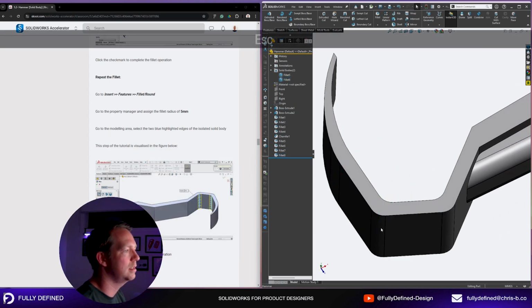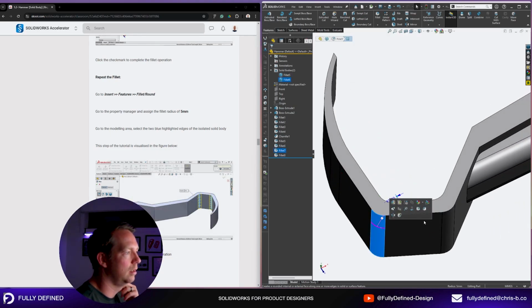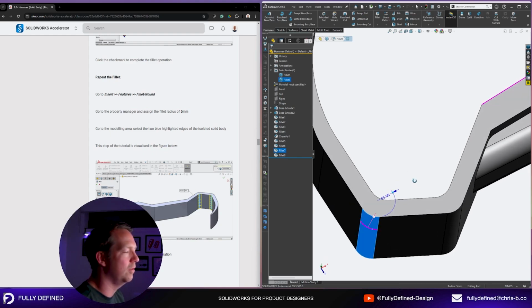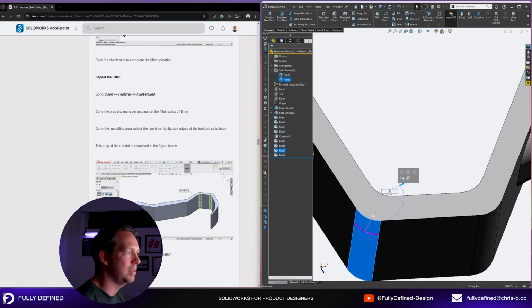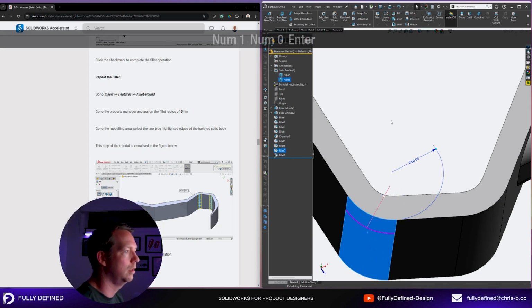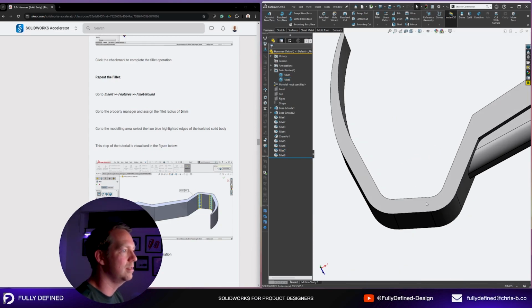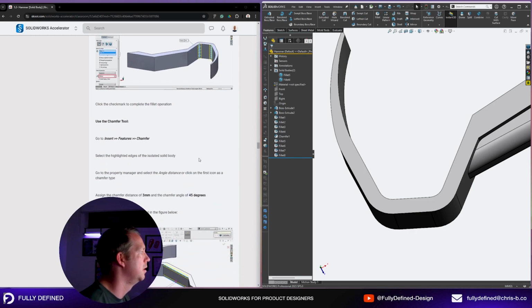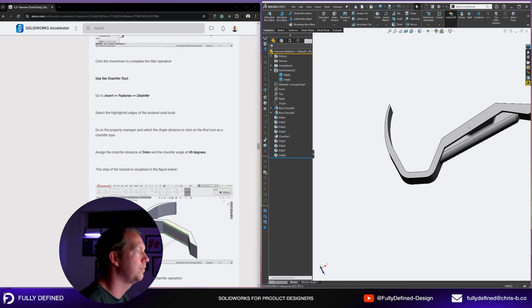So in this example, the product would look better and actually be better manufacturable, if it's like a plastic part or some sort of injection molding, with a consistent radius or a consistent thickness here. So I'd put these up to 10. Okay, you can see then you get a consistent wall thickness through there. So I'm just going to tweak that and keep going.